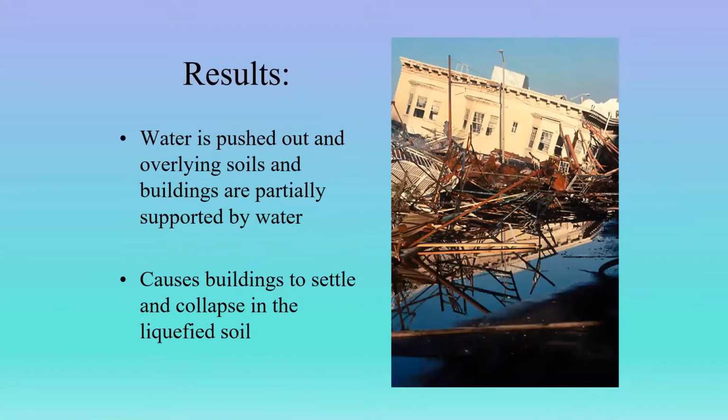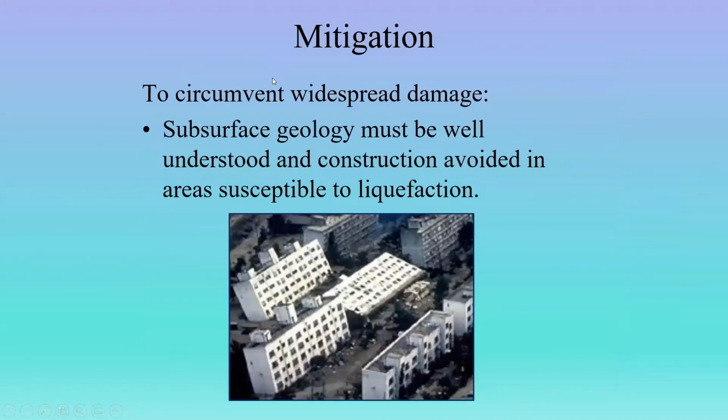Again, what is liquefaction, right? Water is pushed up and out of the overlying soils, so the buildings and whatever's on top of it are then partially supported by water, which is, of course, no support at all. So those buildings, those cars, whatever, then collapse and sink into the ground. The shaking then stops and the ground re-solidifies, and now everything's stuck in the ground, right? So that is liquefaction.